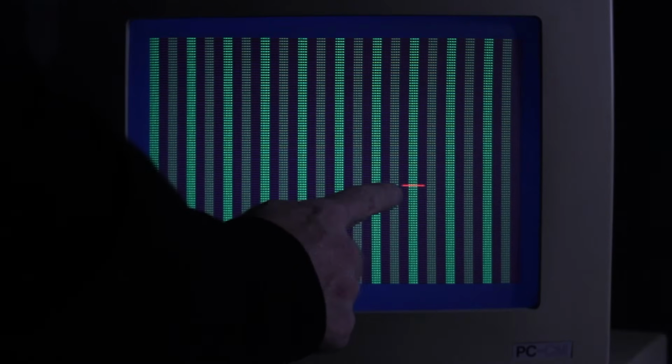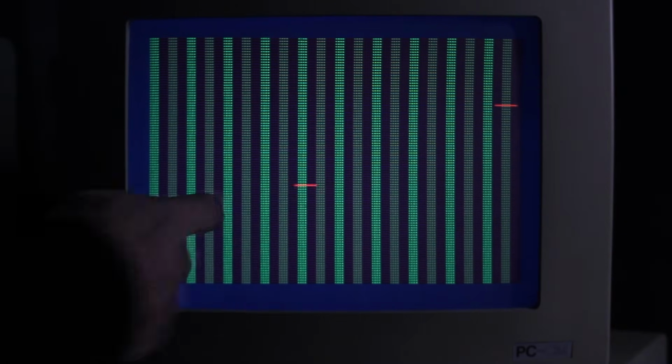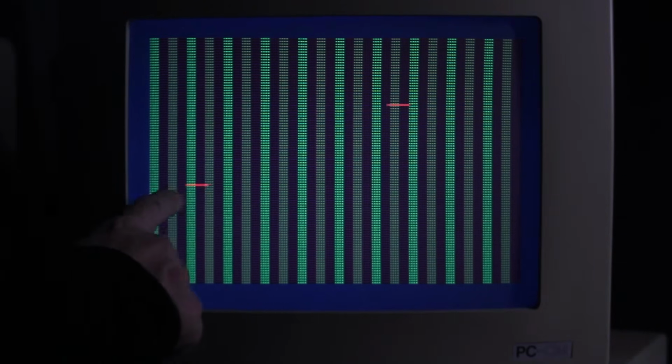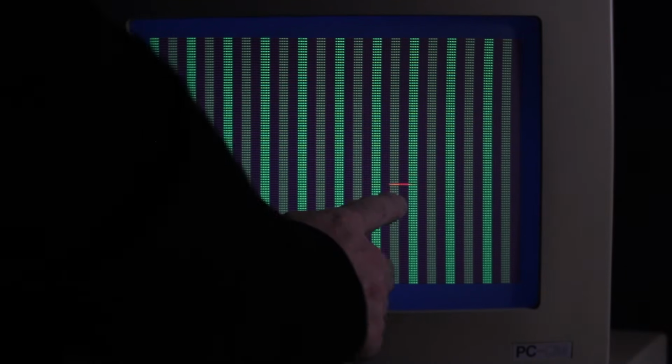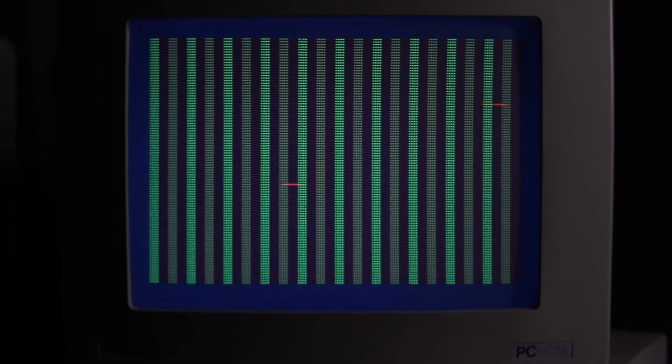When we were changing the background color, for example, I'd change it to red here and immediately back here, but you can see there's quite a bit of delay there, and that just reflects how long it takes to do a port access, and it's also exactly the same amount of time that it takes to do a register write to the CRT controller chip. So we're definitely not going to get control down to the pixel this way.